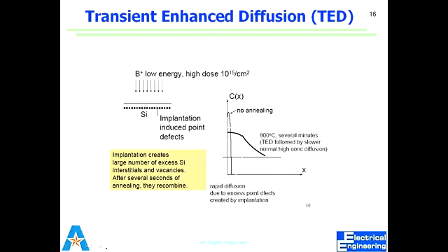So there are many silicon interstitial sites created very close to the surface. So that causes a transient enhancement. Once we introduce them at the start, this is introduction by implantation, not by pre-dep. So that results in many more sites at the surface.